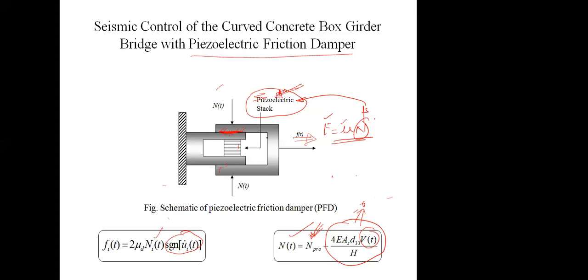Okay, so you only have to make some assumptions. Like if you have to do earthquake analysis, we can directly say that our building will be in the shear mode, so 12EI by L cube will be the shear force coming, and we have to consider only that mode. According to that we can make a matrix for an n multi-story building, supposing a 12-story building, so we can convert it into a 12 by 12 matrix, and then we can make the mass matrix.